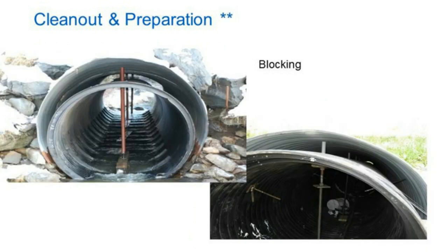An alternative way to block the pipe is the use of jacks to the top of the reline pipe to hold the pipe down, as you can see in these photos. As with rails, blocking can be strapped to the OD of the reline pipe for smaller sizes where it's not practical to attach to the inside of the host culvert or use this type of jack method.